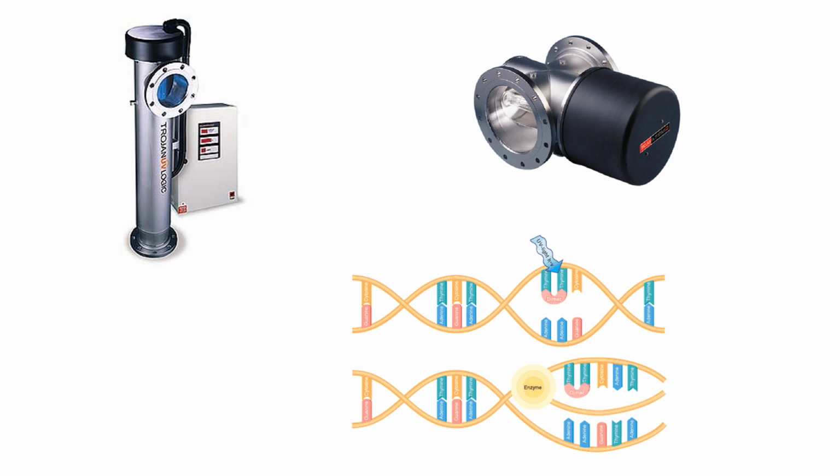And the interesting thing, the way that the UV reactors work, is that they actually fuse together parts of the DNA in the target virus or bacteria or Giardia, Crypto. What they're doing is the UV light penetrates through the cell wall, and then it just so happens that DNA consists of 4 bases, and when you have adjacent thymine, which is one of the 4 codes in DNA.